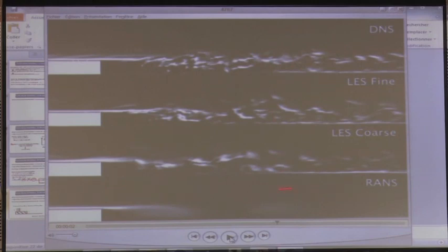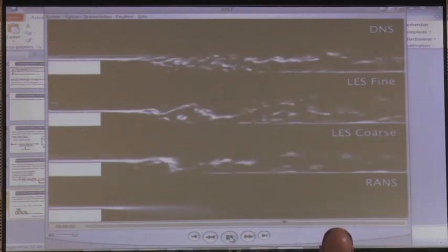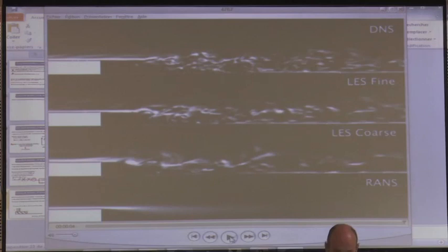So you see here, you don't have anything compared to the real, accurate solution where you have a lot of turbulence. And then you wait. When the steady state is reached, of course there is no steady state in terms of DNS because the flow is always turbulent, always evolving in time, but it will be statistically steady. In the LES, you still have information. Here, you start losing information, and then in the Reynolds-averaged Navier-Stokes equations, you see what you get.